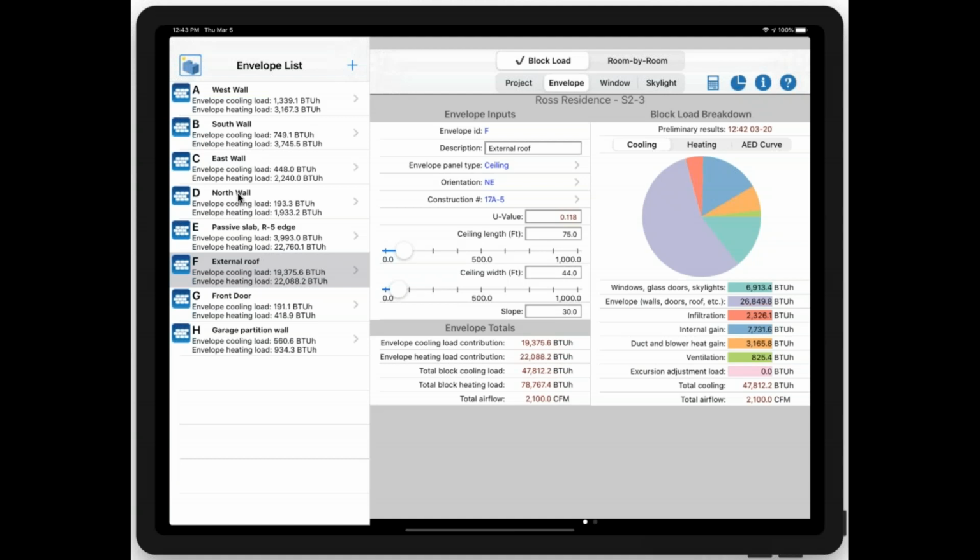If I'm thinking correctly, I think you would add up the U value. I may not be right on this, but do you add up the U values of each of those components in your wall, get a total U value, then do 1 over that to get your R value, or do you add up the R values of each of those and then do 1 over that to get U value? I forget how that works because I think they're either in series or in parallel. You know what I mean? But yeah, there's a way to do it where you add up all the components of your wall to get a final U or R value. Okay. Got it. All right.